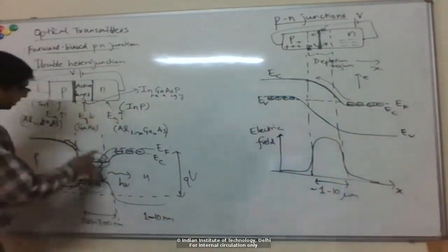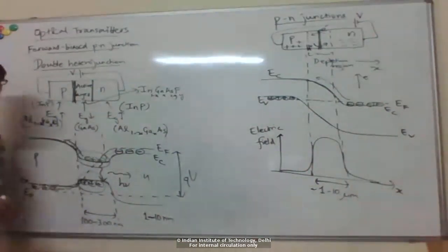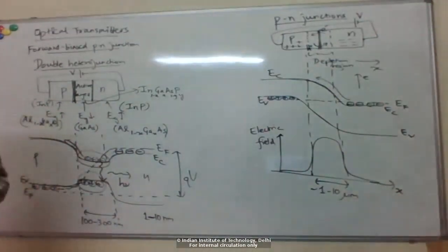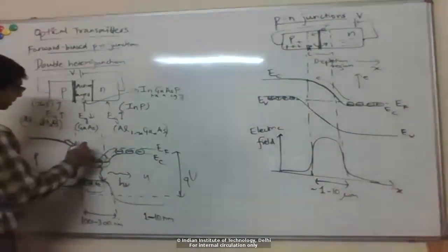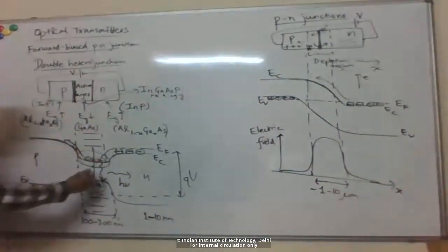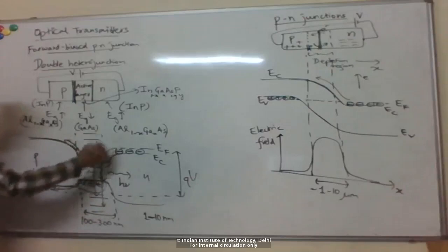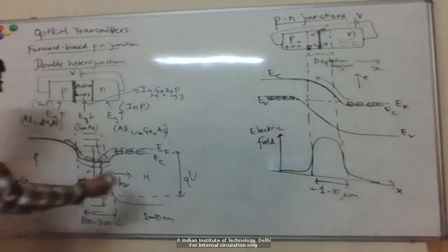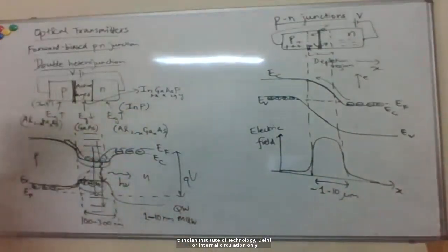Okay, and then once this becomes really thin, right? If you now go down to 10 nanometers or below, the confinement becomes so large that quantum effects for the electron start coming into play, right? So for example, this will be like a potential well here, and when it's so thin, you'll have discrete energy levels within this active layer, right? So now you can see that there will be only specific transitions which can happen, which are the allowed energy levels in this potential well. Okay, so those are known as quantum well structures or multiple quantum well structures, which are also made for some specific applications.